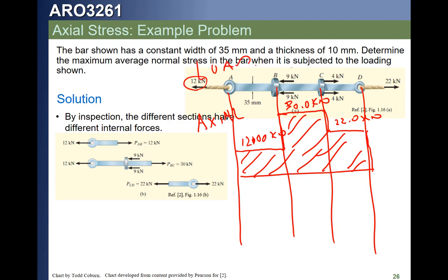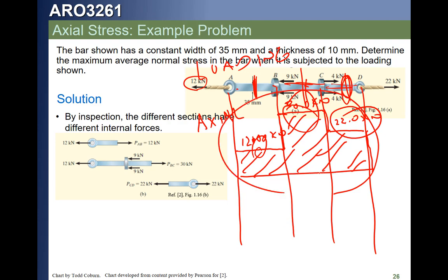Now, once you have drawn this curve, it's really easy. You can figure out the stress in this member, or this member, or this member. At this cut, we're going to have the area of this part with this force. Any cut between here and here, we'll see this area with this force. And any cut between here and here, we'll have this area with this force. See that? If we hadn't carefully, systematically figured out what the axial loads in the part were first, we would have probably gotten a wrong answer, even if we understood the rest of the procedure.